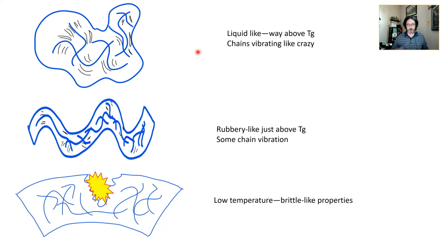And you can actually pour it. I say it all the time, and everyone else does too: melt down the polymer. Well, it's not really melted. It's just that the chains are vibrating like crazy, and they can move really, really easily. And so you can actually cast it, and you can injection mold it, and do stuff like that.